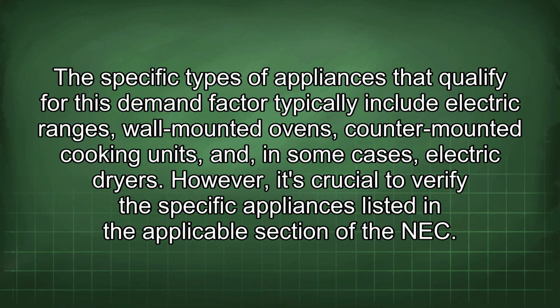The specific types of appliances that qualify for this demand factor typically include electric ranges, wall-mounted ovens, counter-mounted cooking units, and, in some cases, electric dryers. However, it's crucial to verify the specific appliances listed in the applicable section of the NEC.